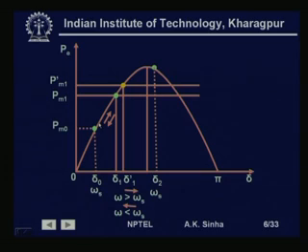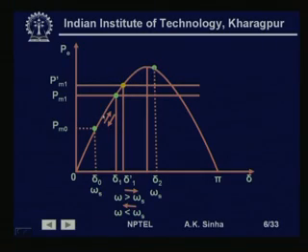So, as it accelerates, the delta angle increases. The electrical output will also increase, that is Pe will increase. Now, this will keep on happening, that is delta will keep on increasing, because still we have more mechanical input to the system and less electrical output. This will keep on going till we reach this point.